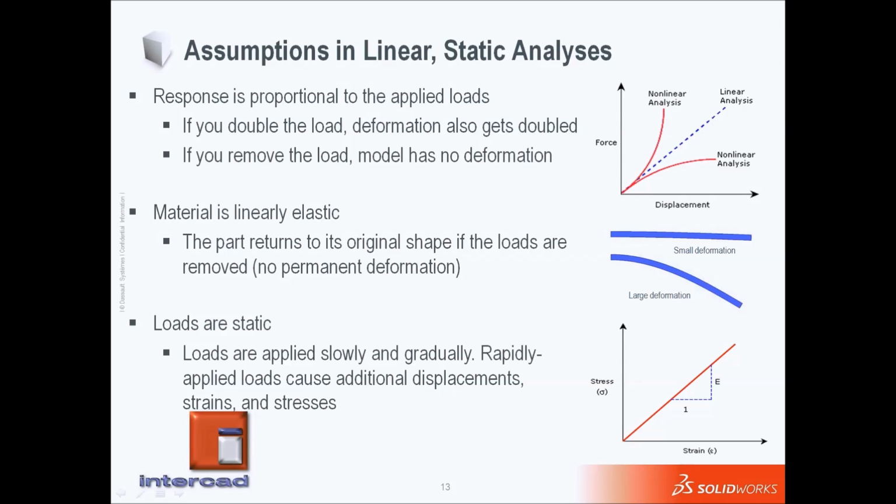And the third point is about static load. The static load assumption means that the loads are applied slowly enough for the inertial effects to be insignificant. Therefore, any fast loads, like when you do a drop test or strike a nail with a hammer, where we have amplification of the load because of the speed, are not cases of static loads.